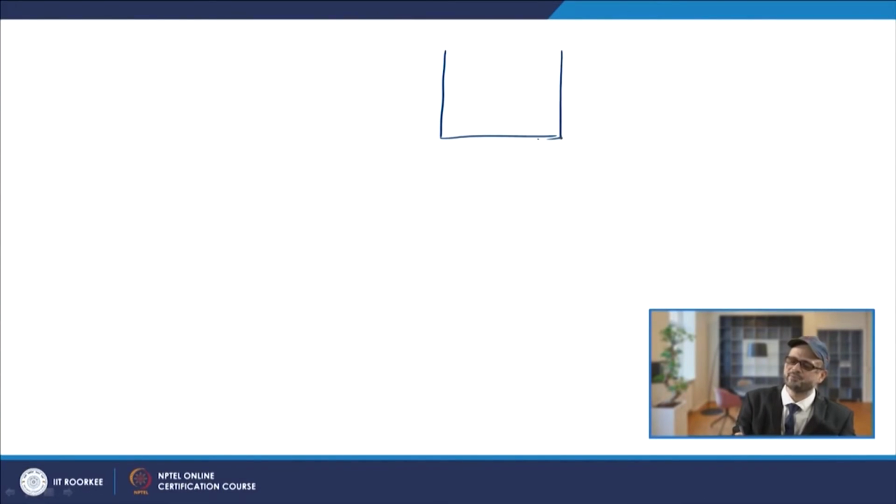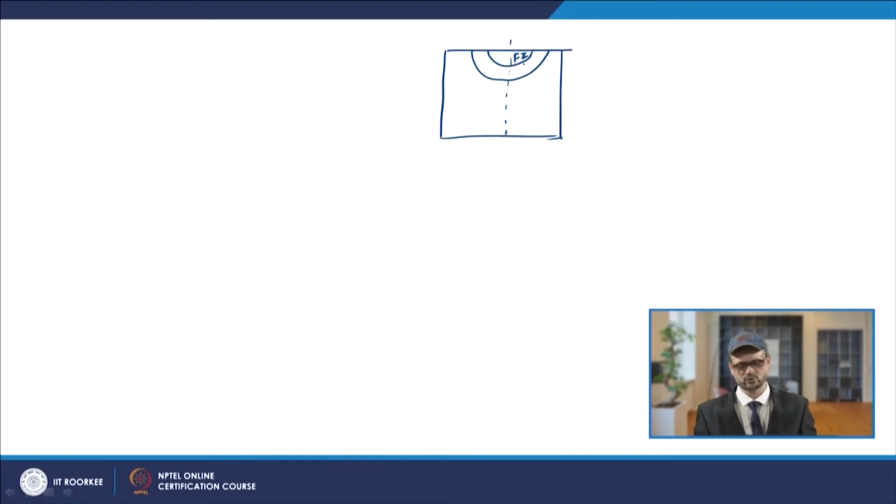This was done for 1040 steel, and when the fusion zone and HAZ were measured, it was seen that without preheating the zone was a little narrow, whereas with preheating that zone became wider. You can understand by referring to a schematic figure: your fusion zone earlier was this, and your heat affected zone can be shown this way. You have some temperature also in those zones.